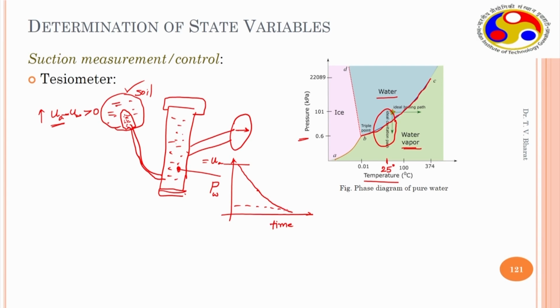When it reaches the vapor pressure, maybe 3.1625 kilopascal at standard temperature, this is the saturated vapor pressure, uv sat. Depending on the RH, you may have some uv value slightly less or significantly less than 3.1625 kilopascal at standard temperature.